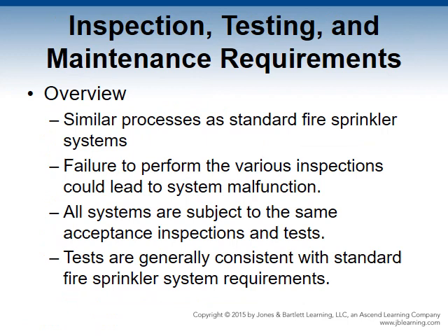Inspecting, testing, and maintenance requirements. With few exceptions, specialized water-based fire protection systems go through similar processes as those used for the approval, periodic inspection, and maintenance of standard fire sprinkler systems. Failure to perform the various inspections and tests results in an unknown operational disposition of the systems that could lead to system malfunctions.